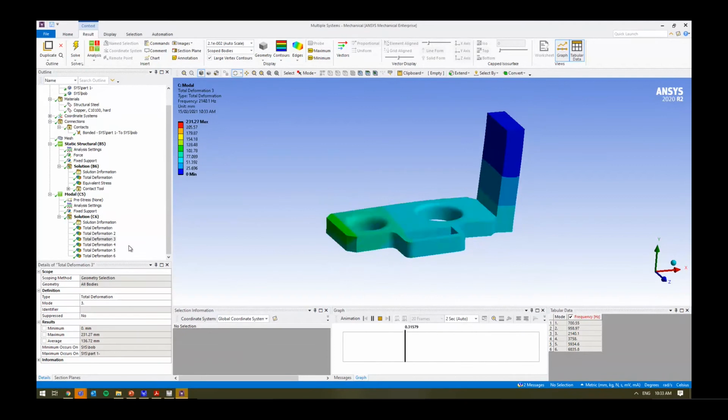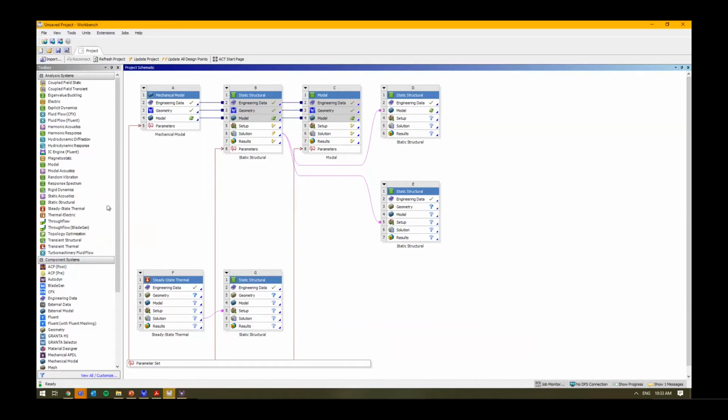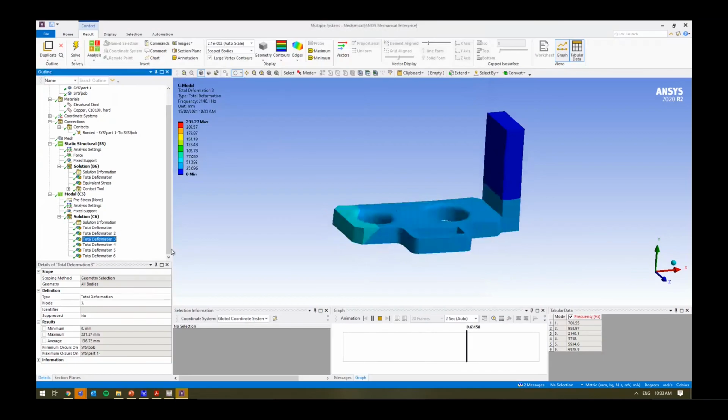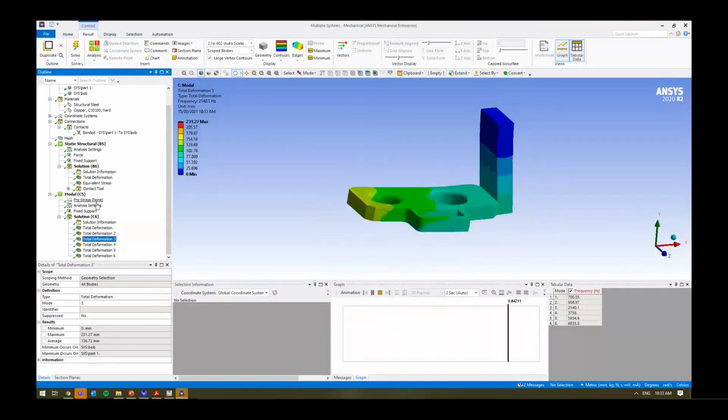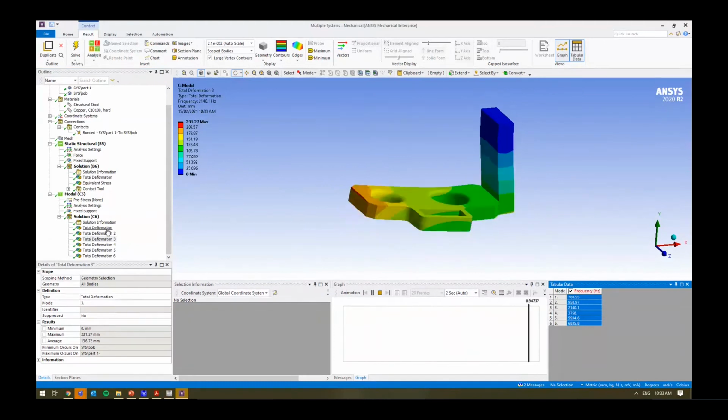If you want to understand what the actual displacements or stresses of a system might be due to vibration, we'll have to apply a harmonic analysis or a response spectrum. Again, these are things that will probably be talked about in Peter Brand's session. The modal analysis will tell you, depending on your loading condition, what the actual frequencies might be. It won't necessarily tell you this is the stress or this is the displacement that you're seeing at all, right?